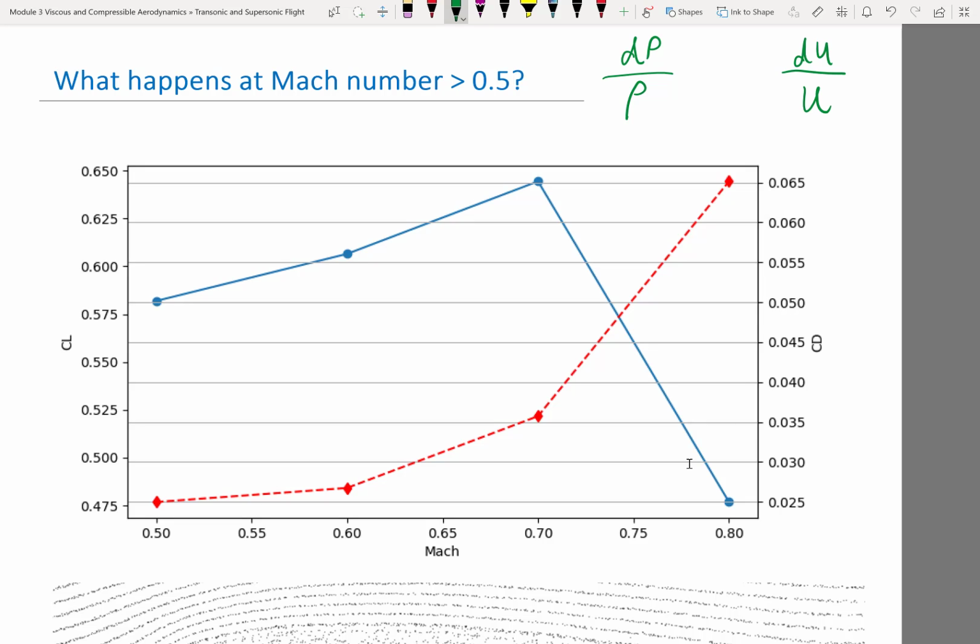More than 8, right? Why is it more than 8? Why do we have a speed increase of more than 8 when the contraction ratio is 8:1? Yes? Because density dropped, right? And the reason density dropped is because pressure dropped. So what is driving the flow to go from a low speed at the bigger cross-section to high speed at the smaller cross-section is the pressure gradient, right? The pressure was high upstream and low downstream. That's what accelerates the flow.